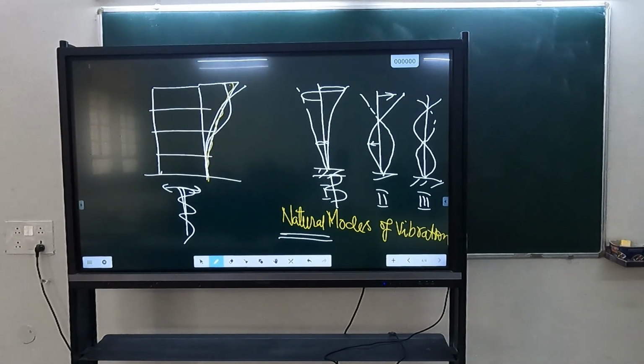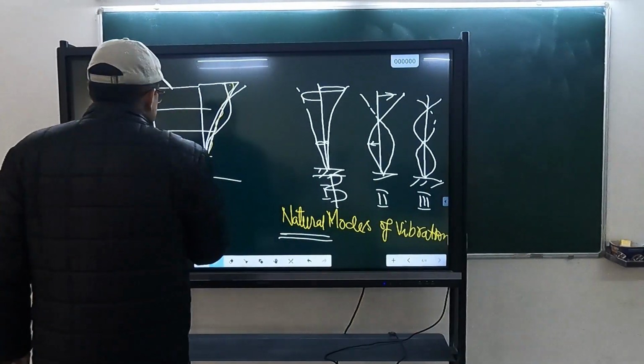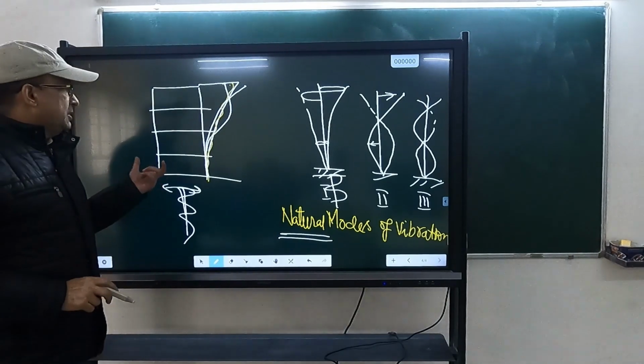So you just look at that. We get a very high peak in the response spectrum. PGA increased, but the increase in PGA was not that much. The increase in spectral acceleration was much higher. This is called filtering action. The same thing is going to happen here also. So what will happen?